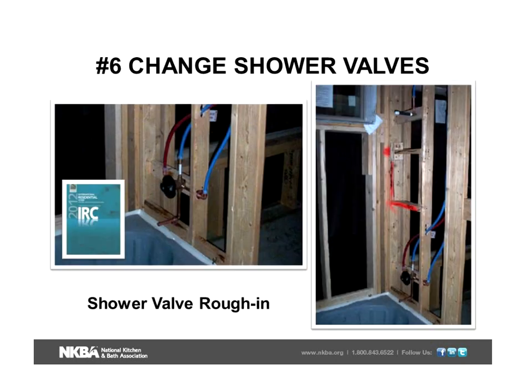So let's talk about those issues at this point. I want you to notice, and again, this is required by code for tub shower, and you can see that it is a tub shower combination. Notice that all of the connection is made on the inside of the bathtub area, not from the back side. That means that if this had to be repaired, you'd have to do it from the inside of the tub area.